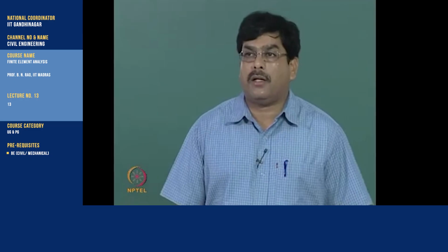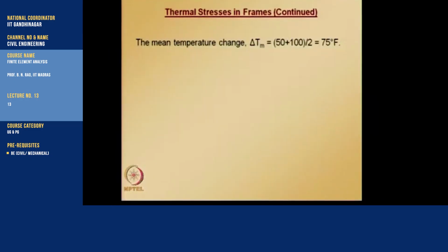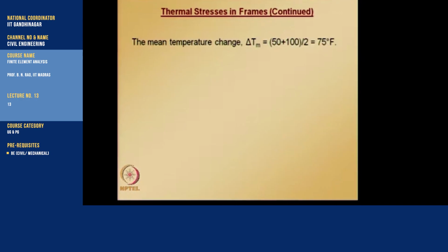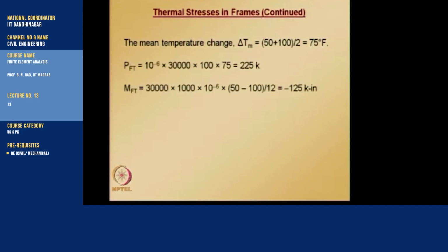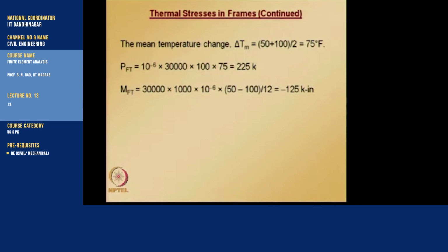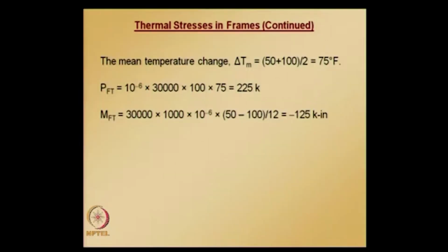So now let us note down something, what is the mean temperature. This information is given, top side and bottom side temperature change. So using those we can calculate what is the mean temperature change, and once we have this we can calculate what is PFT, and please note that this PFT is not dependent on length of the element. So PFT value is going to be same for both element 1 and element 2,